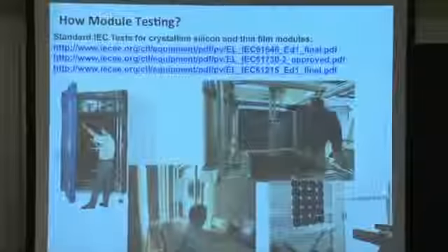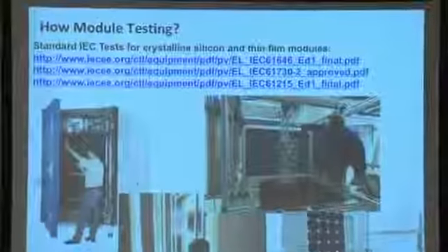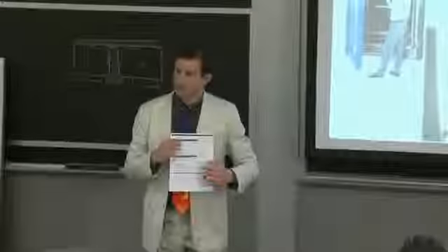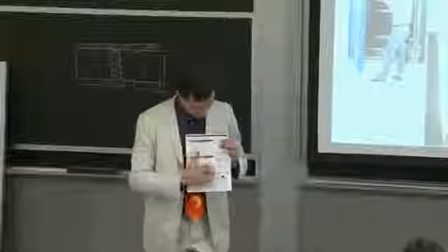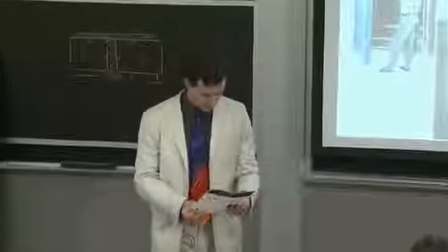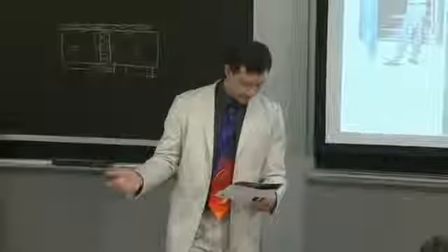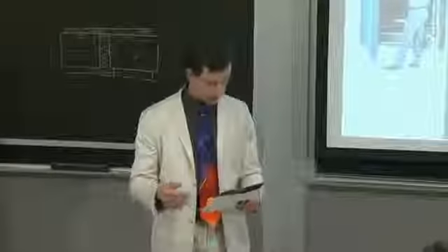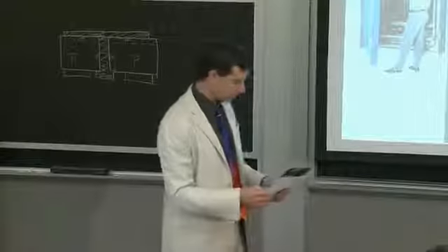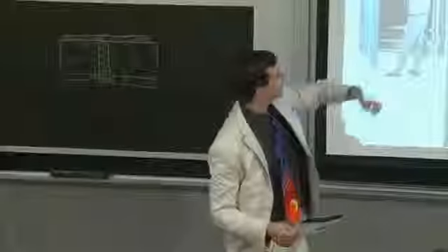And you'll see on the back of certain spec sheets, like this one from First Solar right here, the different testing agencies that have certified the module, right? These little logos represented. So it says it's UL certified, CE mark, certified according to IEC spec 61646. That's the one right up there at the top, and so forth.